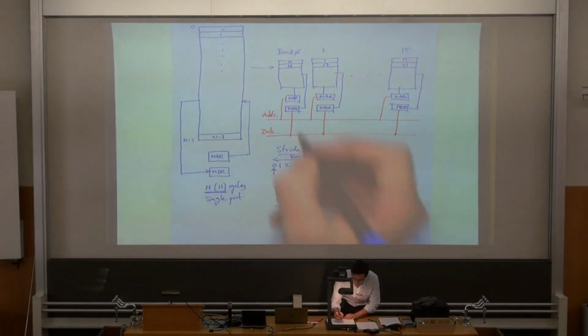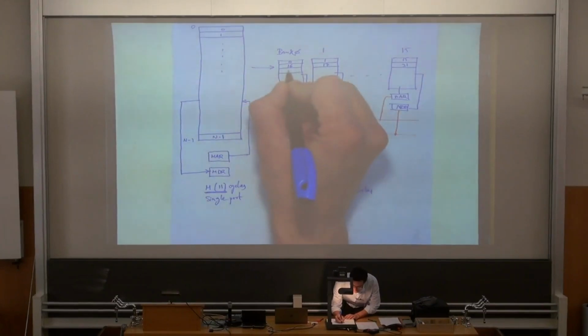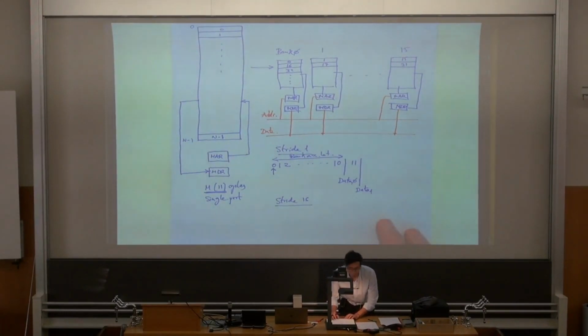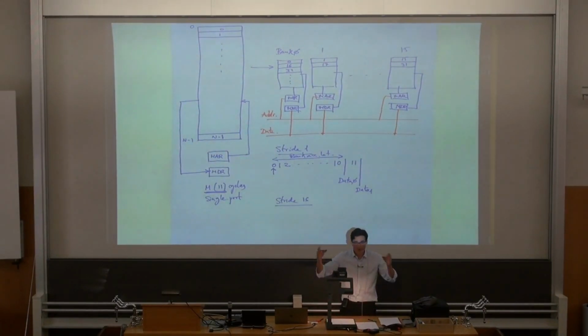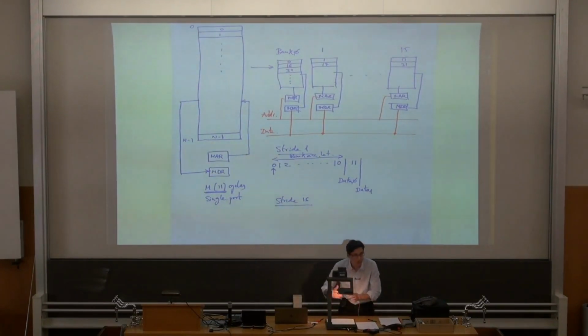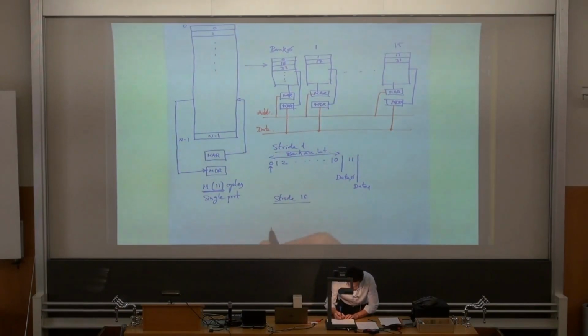It turns out that all these elements are stored in bank 0. So it will be impossible to avoid the entire bank access latency for all the elements that we will be reading from bank 0. We will start the access to element 0 in cycle 0.